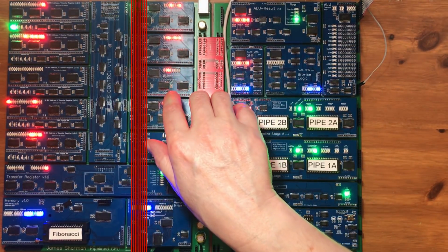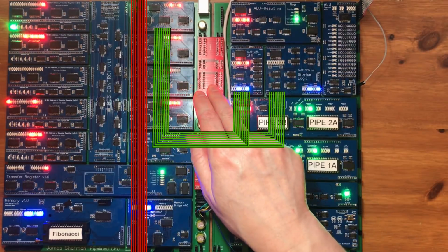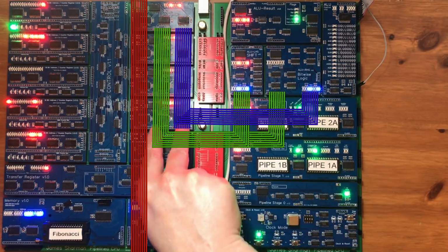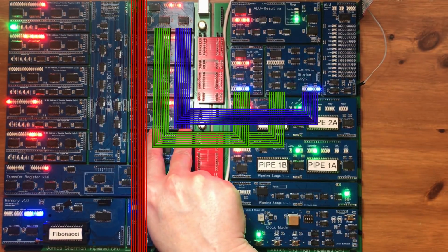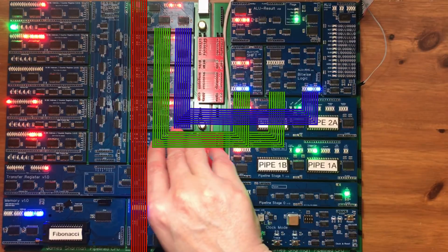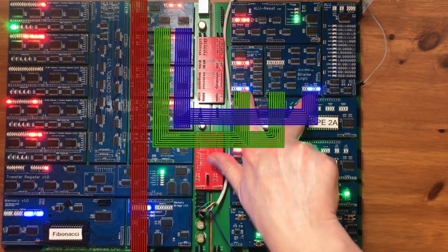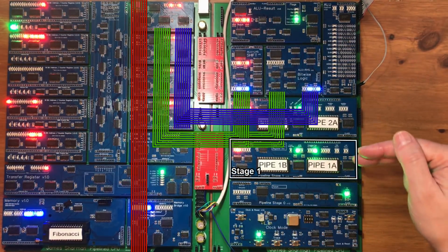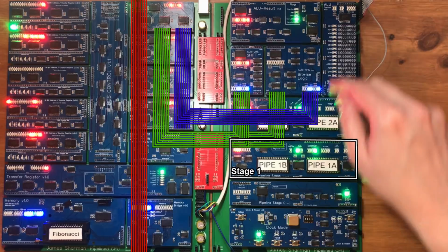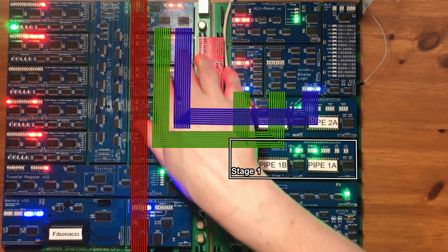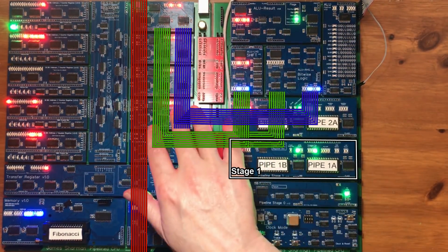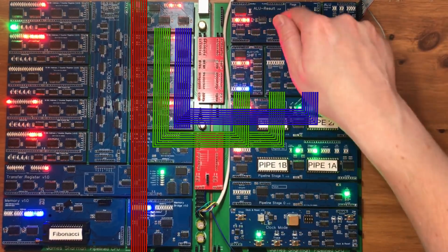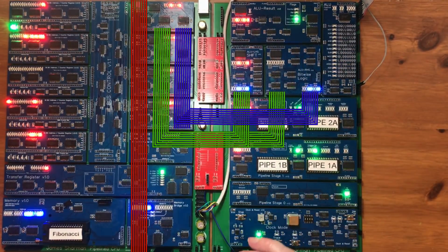Then you've got the buses that I call LHS and RHS. They just extend down this far, and any of the 4 general purpose registers can push their value onto either of those buses, and those 2 sides are the 2 inputs over here to the ALU. So the ALU operation is kicked off by pipeline stage 1, so it can select any of the ALU operations, and it can select any of these 4 registers for either the left or the right hand side input, and then in the next cycle the result can be written back to any other part of the processor.